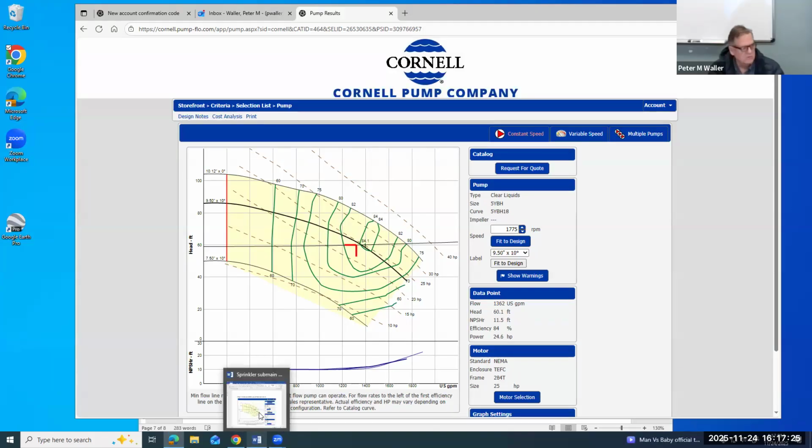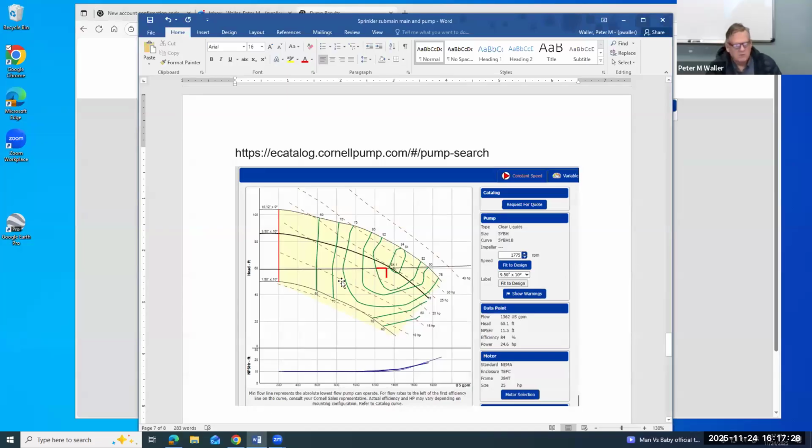Why do you open the valves slowly? What you don't want to do is introduce water really fast into your pipeline, so it's flowing all the way down to the end with no back pressure, and then flowing up to the end, and then suddenly stopping, because that's when your pipe gets blown out of the ground. So you have to fill your pipe slowly. That's water hammer. Yeah, and there are programs in the Excel spreadsheet that do water hammer calculations, but we're not going into that for this project. Okay.